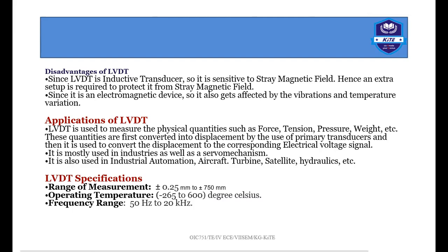Yes, that's the reason. The application of LVDT is to measure physical quantities such as force, tension, pressure, weight, etc. These quantities are first converted into displacement by the use of a primary transducer, and then the LVDT is used to convert the displacement to the corresponding electrical equivalent. It has been mostly used in industries as well as in servo mechanisms. It is also used in industrial automation, aircraft, turbines, satellites, and hydraulics.